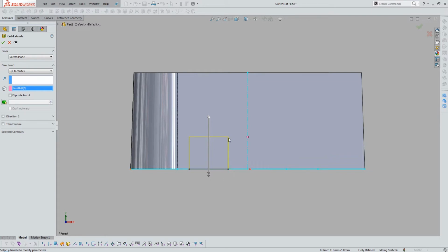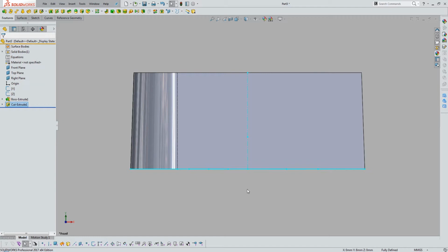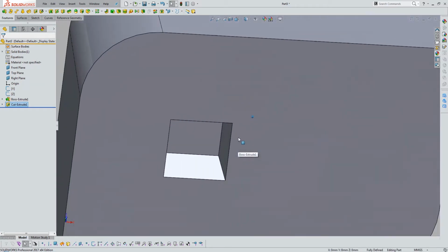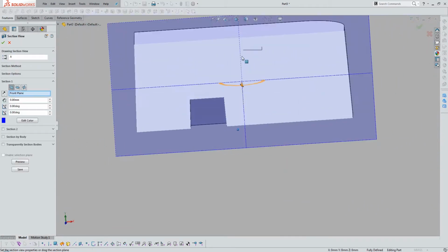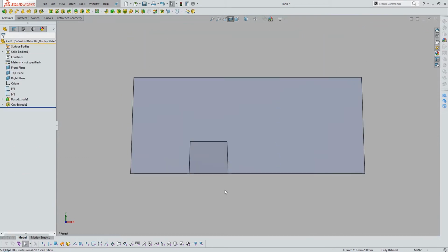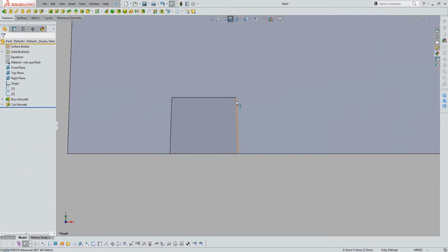And we know lines that are parallel to the direction of pull, which is to say I'm going to pull the tool that creates this feature down out of the part. These parallel lines will cause a lot of friction and potentially damage our part or our tool. So I'll throw a draft angle on there. So that's method number two, is to create cut parts which are drafted by default. Now you can see these lines are not vertical, instead they're going outwards.